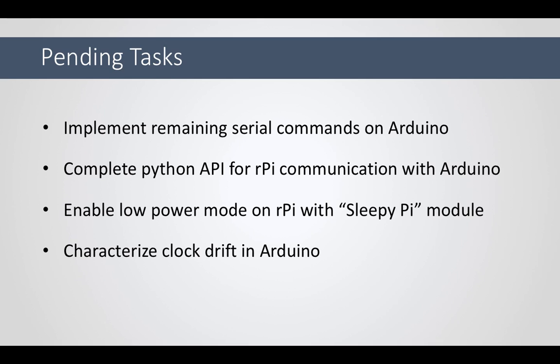I have a few more tasks before my project is complete. These include implementing the rest of the serial commands on the Arduino, writing a user-friendly API for serial interfacing on the Raspberry Pi, enabling low power mode on the RPi by attaching the Sleepy Pi attachment, and characterizing the Arduino's clock drift against temperature.